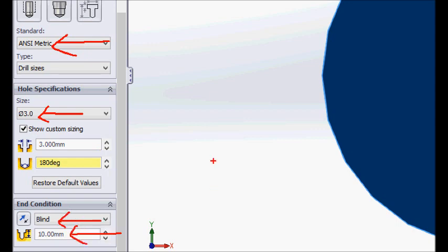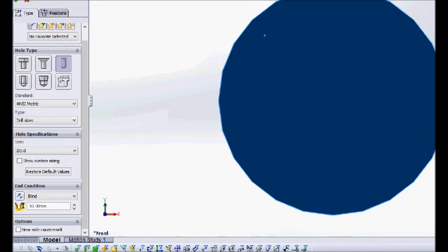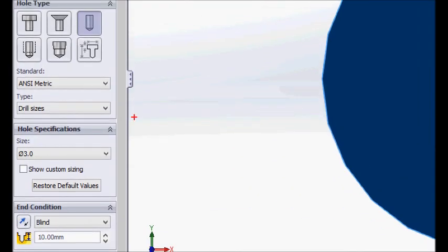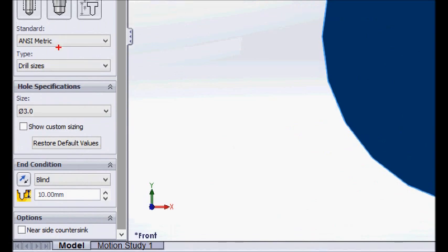Right? So we're on page 175. We want to place a hole. We're going to place a hole using the hole wizard on the features ribbon. Remember I talked about the hole wizard last week. The hole wizard is one of the tools that's kind of a reverse polish tool, right? You want to select the plane before you select the tool. So we want to select this face right here before we select the hole wizard. Otherwise, your hole might not place correctly.